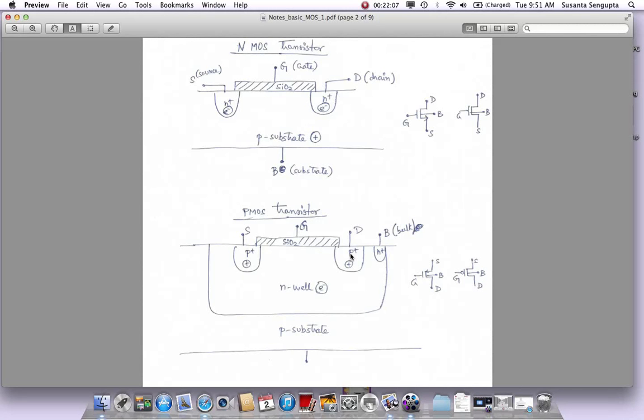Okay, that's what a hole is. So here we have less electrons, right? Here we've got a ton of electrons. So if it's holes and you wanted to cause a current from source to drain by holes, you can't, because this region is off. It is devoid of holes, it's very rich in electrons. So again, you have made a PMOS transistor, which is off.